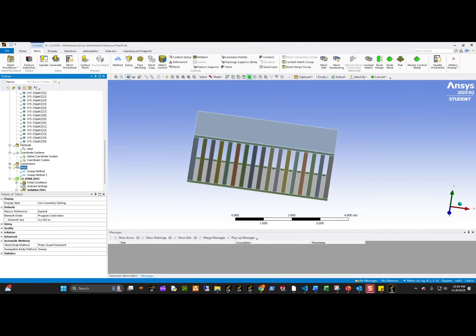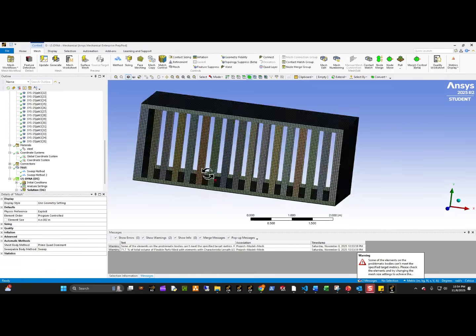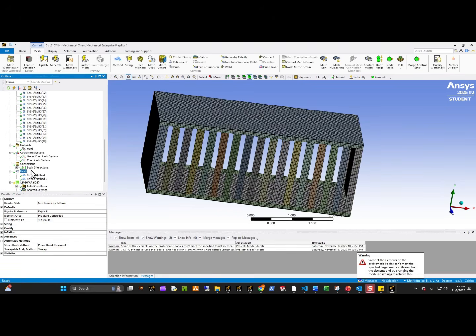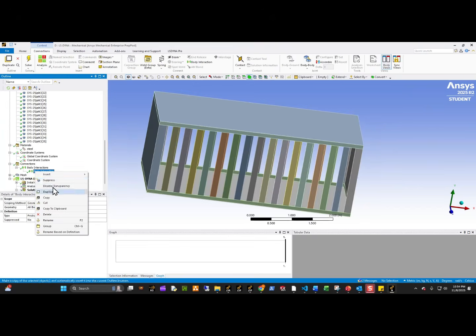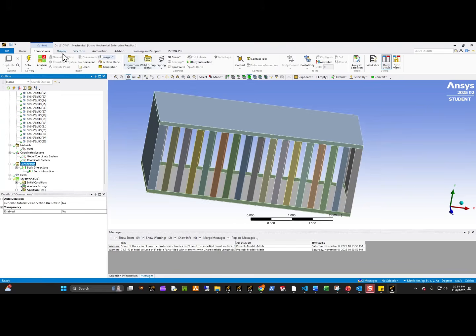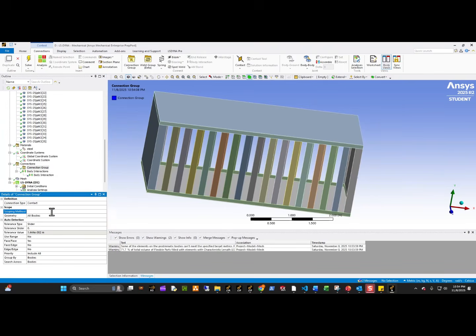And then for the mesh here, I'm going to use 40 millimeter, and I'm just going to mesh it. This just creates the minimum amount of elements required for this type of analysis. What I'm also going to do is take advantage of the auto contact detection method inside the Workbench mesh to basically do all bodies.